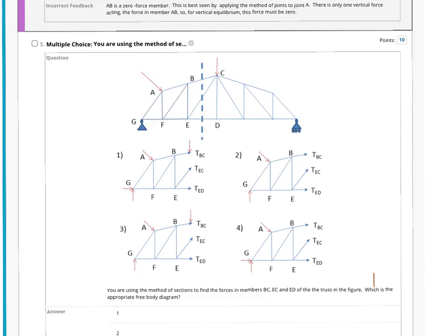Two things to note in this case. First of all, for the free body diagram of the left hand side of the cart, whether the support reaction forces are truly represented. Now the support at G is a pin, so it should have a vertical reaction force and a horizontal reaction force. Both are possible. Now whether they will have or not depends on the load that has been applied. So if we apply that criteria, then you'll see this is one candidate and this is another candidate.